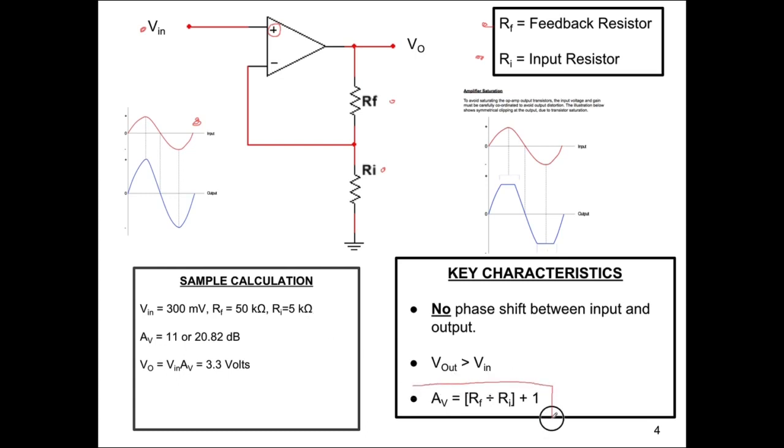We're going to go over this quite well in class. It's a real easy formula. Here's an example, so you can just follow it through. You can express the voltage gain as a ratio or in dB. Notice that the input and output have the same phase relationship. If you overdrive the amplifier, you're going to get distortion and clipping. This is not what you want.